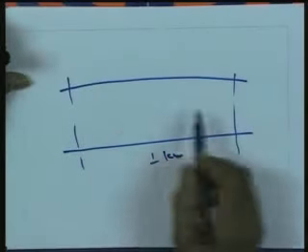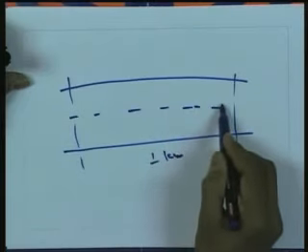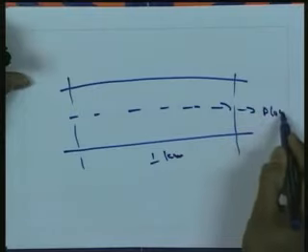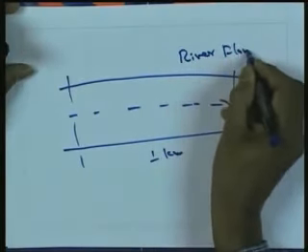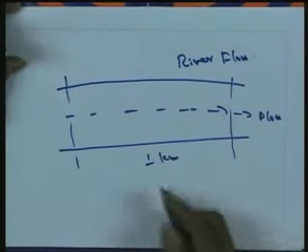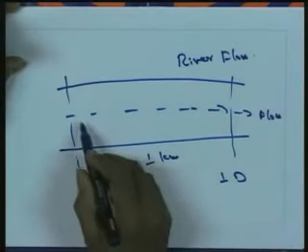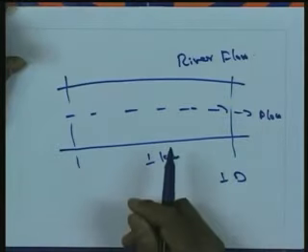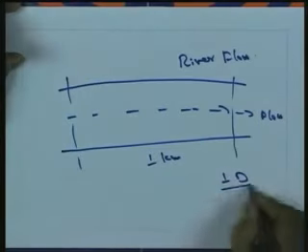In this particular case, if you are interested only in what happens in the direction of the flow, say if the direction of flow is in this direction, then even though the river flow is 3-dimensional, depending upon the particular problem we are solving, we can analyze it as 1-dimensional flow. That means in this direction of flow we can consider the variation of the 1-dimensional parameters, since it is more important for this particular problem.